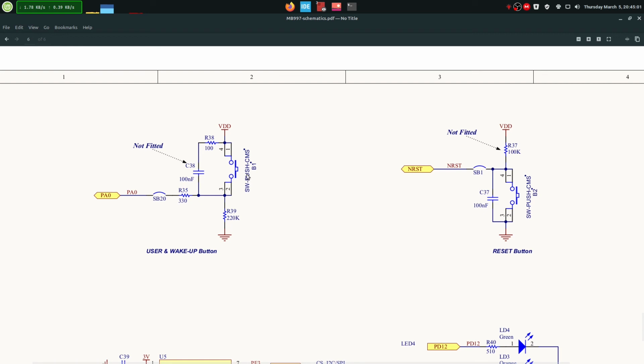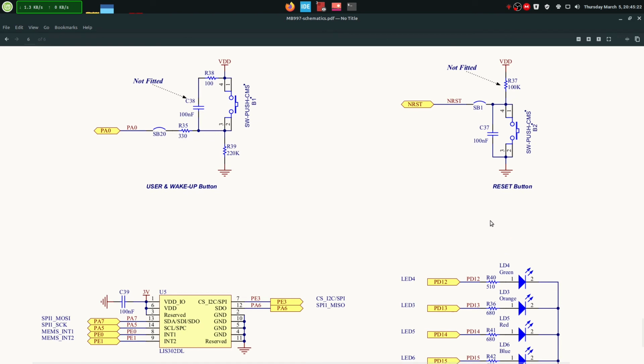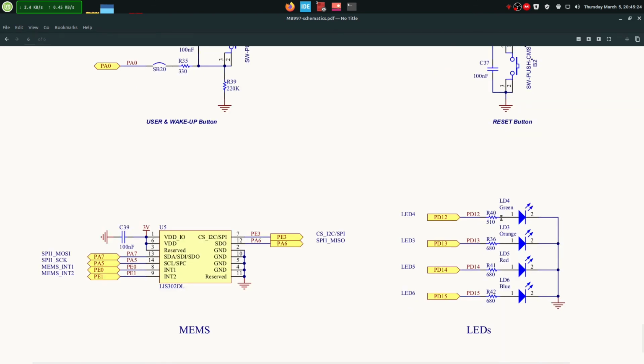So when you click the button, when the button goes into the state 1, the input goes to the state 1 again. So this is active high in this case, and the reset was active low, because when you closed the button, the state 1, the input pin was actually going to the state 0. So this is active high and that is active low. Similar with LEDs.